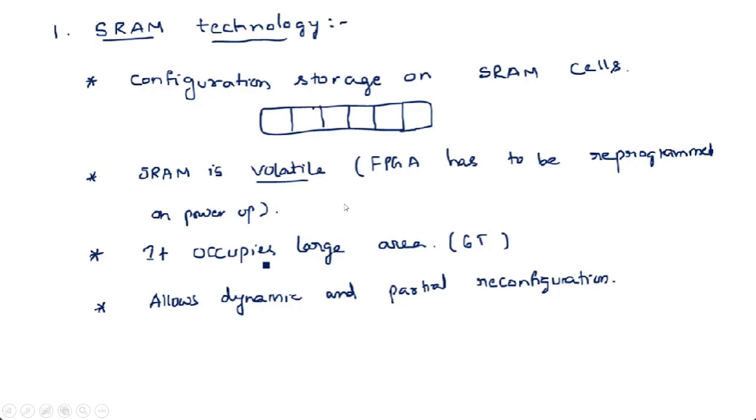Basically, the latch is connected with two inverters, no? One inverter is designed with a CMOS circuit, one PMOS and one NMOS. PMOS is pull up and NMOS is pull down. Like that, two inverters are constructed with four transistors, two CMOS circuits, and two more pass transistors.